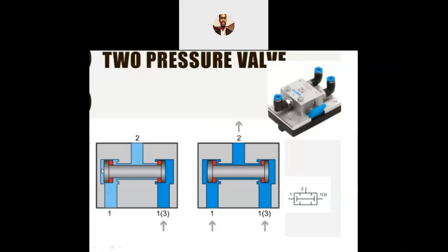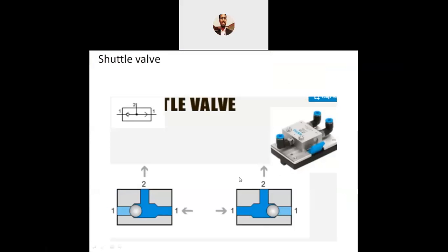Whenever the first piston is on the leftmost position, it is an open position for the passage 1. When this first piston is on the leftmost position, this third piston will be closed. When this third piston moves to the rightmost position, then the way for the first piston will be closed. See, this is how it operates and controls the pressure.